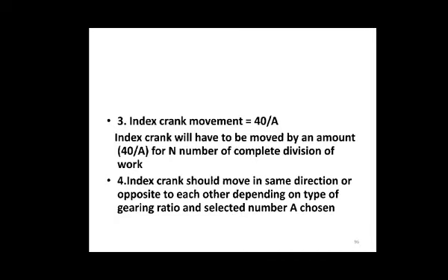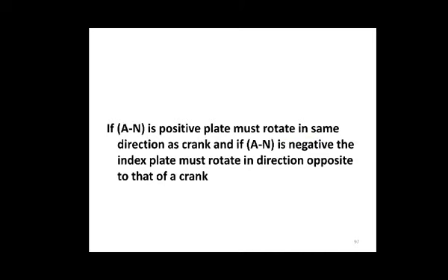If A minus N is positive, the plate must rotate in the same direction as the crank, and if A minus N is negative, the index plate must rotate in the direction opposite to that of the crank. To achieve these conditions, the number of idlers used depends upon this.